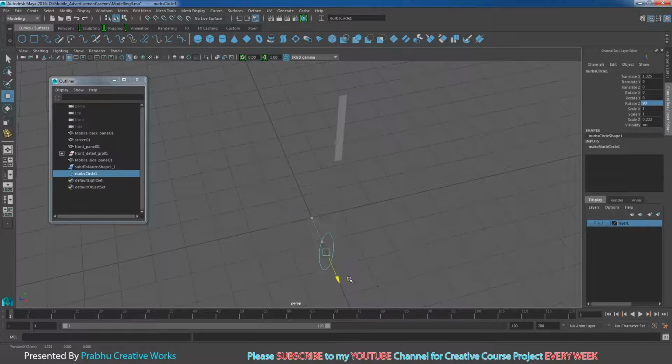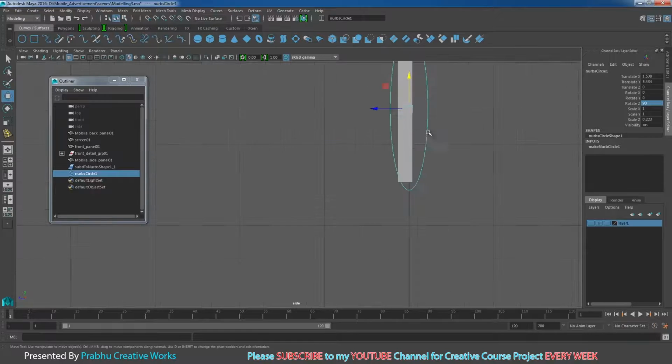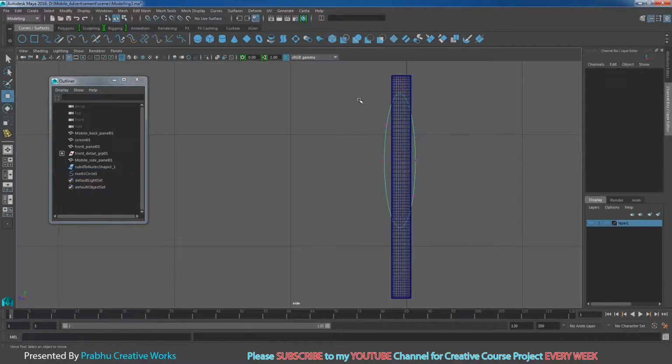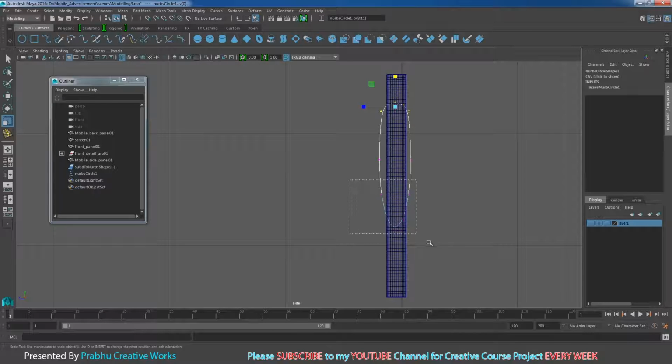Press W and move in X, and move in Y. Go to right view. Now you are able to see clearly what we have. Press R on the keyboard and scale in middle. Press 4. Press W, you want to move up. Right click and choose control vertex. I will select these 5 control vertices, press R and scale in X. You want to do the same thing on the bottom side. Select these 5 control vertices and scale in Y. Then select these 5 control vertices on this side and scale in Z. Select these 5 control vertices and scale in Z.